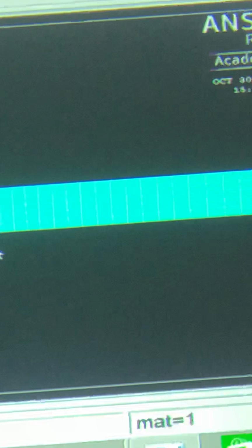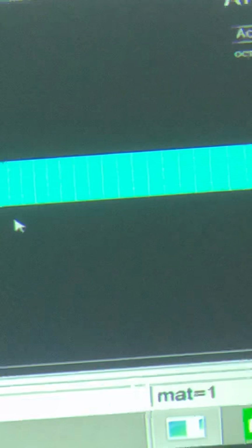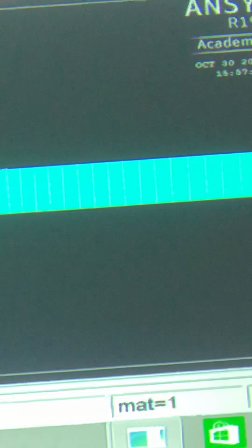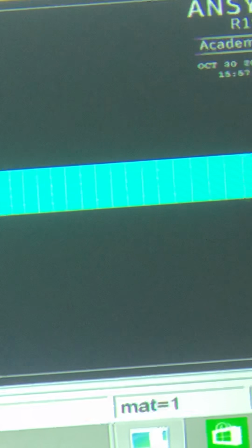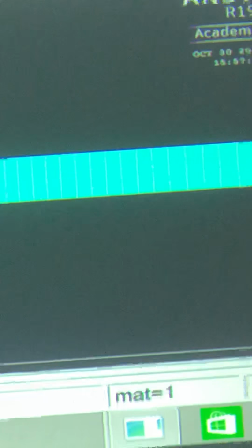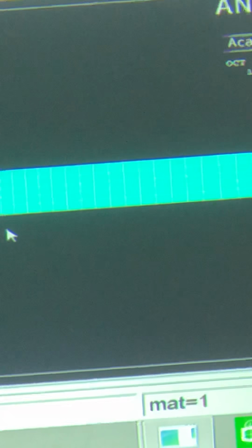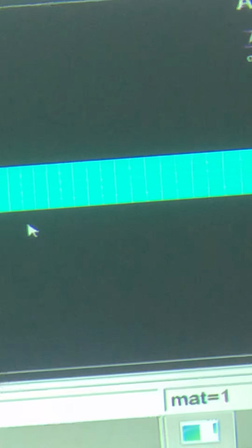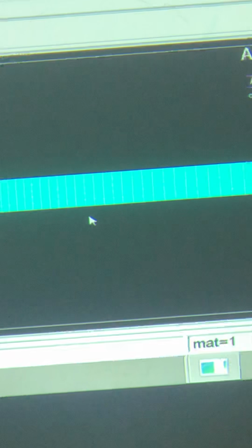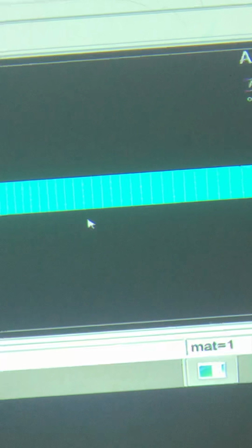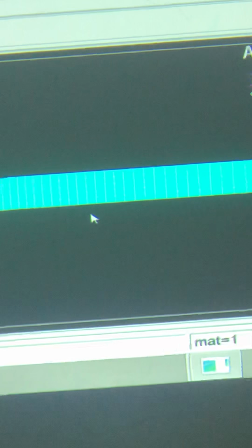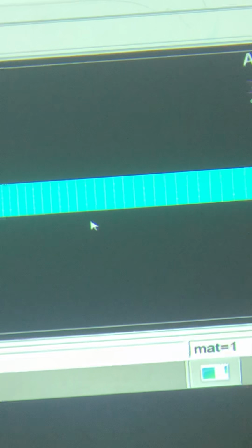So the physical model is one part, but we divided it into 50 multiplied by 5, so it means it will be 250 elements, right? But based on Ansys, when we select the types, it just shows me one type. Yes, this is one element type, but we have 250 elements.